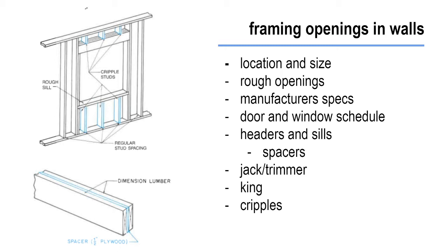The architect would also include a door and window schedule that would list all of the doors and windows in the house, usually with the nominal dimensions. They would also be identified on the floor plan by a mark of either a letter or a number. All doors and windows of a certain size and type would have the same mark.